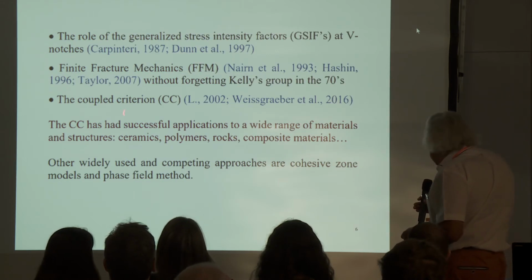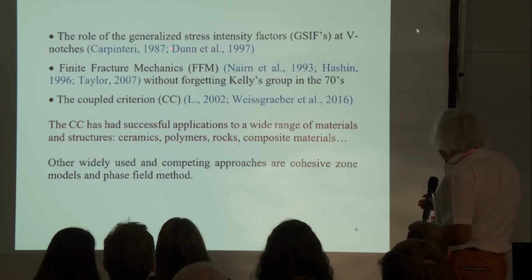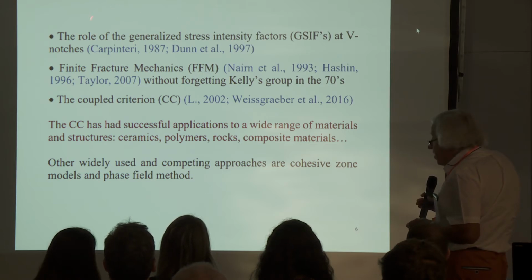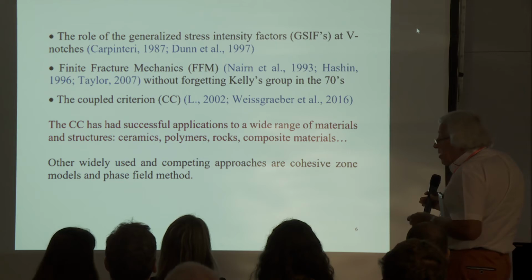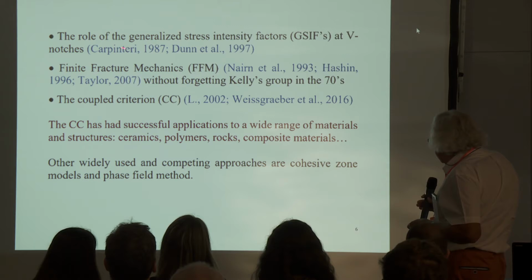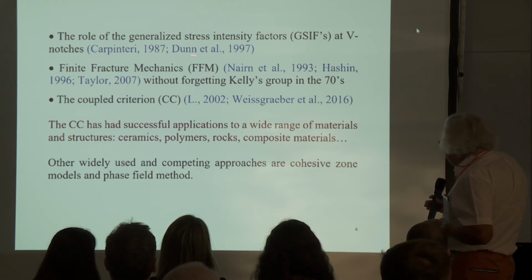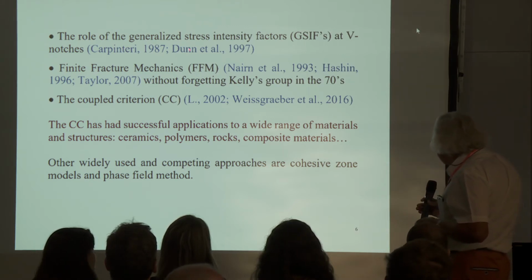I have to mention also the works on the role of the generalized stress intensity factor, I mean the intensity factors involved in the Williams expansion in all cases, not only the crack, but even the V-notch. I can mention the work of Alberto Carpinteri here, and this very important experimental work by Dunn and his group.